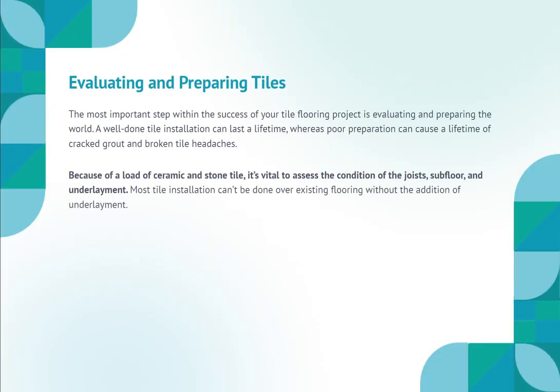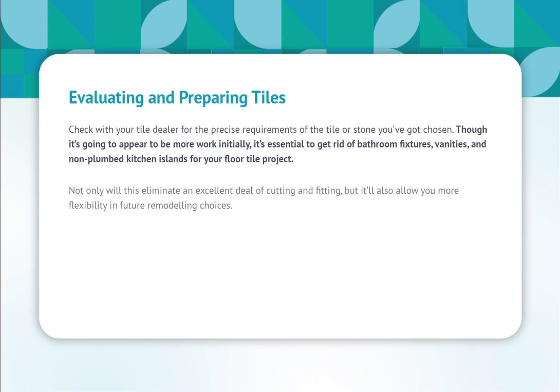Evaluating and preparing tiles. The most important step in the success of your tile flooring project is evaluating and preparing the floor. A well-done tile installation can last a lifetime, whereas poor preparation can cause a lifetime of cracked grout and broken tile headaches. Because of the load of ceramic and stone tile, it's vital to assess the condition of the joists, subfloor, and underlayment. Most tile installation can't be done over existing flooring without the addition of underlayment. Check with your tile dealer for the precise requirements of the tile or stone you have chosen.